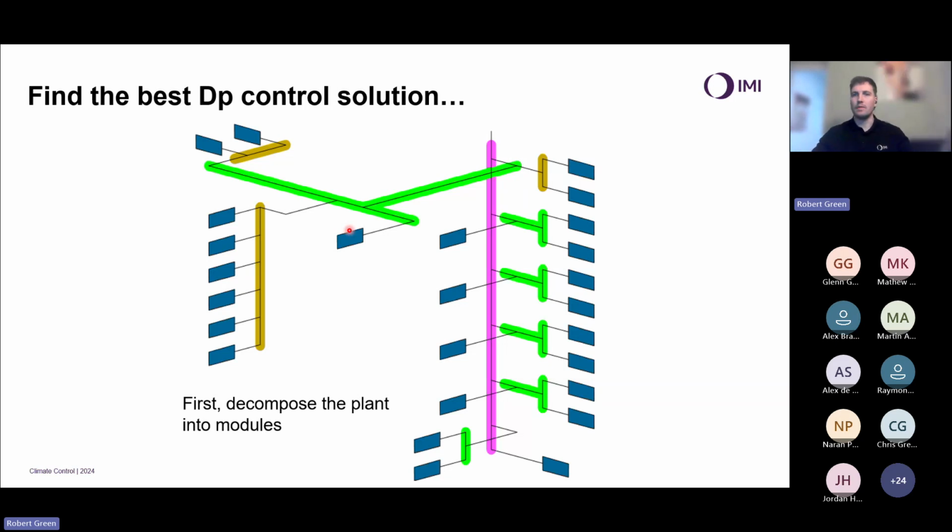But we leave everything else open. That's not going to necessarily solve the issues you have here, because water's fundamentally lazy. If it's got to do more work to get through the DPCV here, it's going to short circuit that and go to other areas of the system. So let's have a look, and let's start with the minimum amount.